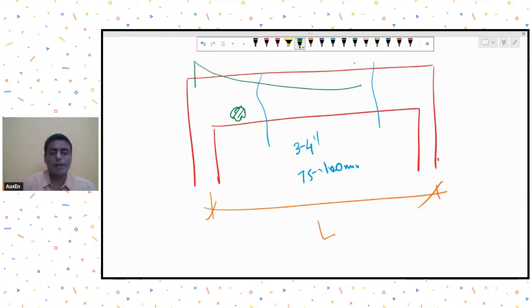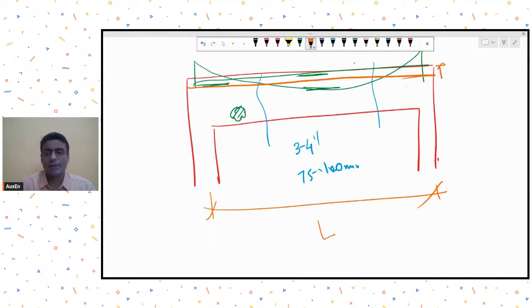So if my bending moment diagram in a beam was like this, hogging, sagging, hogging maybe. Hogging means compression is at the bottom in the hogging zone. Sagging means compression is at the top. I do have the slab also over here, this is my slab thickness also. So typically if I want to remove some sleeve from here, I would like to do it in some zone which is near the point of contraflexure.